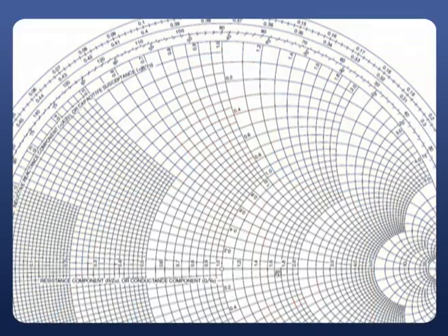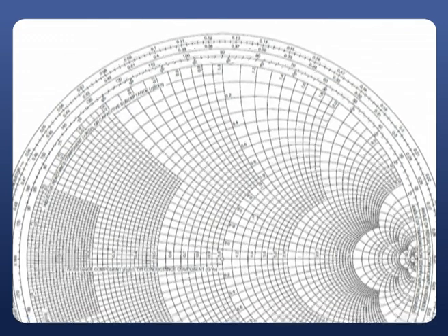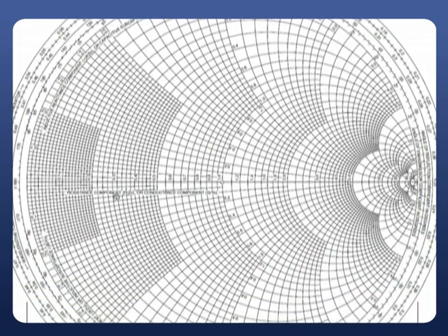Now, using that circle you can easily identify the standing wave ratio. How to identify the standing wave ratio using that circle? Just observe our Smith chart, and see where our circle meets the real axis. Whenever I draw a circle with this radius, the circle may lie like this. This is the imaginary circle that I am drawing, so actually it is not existing here. You can imagine a circle with OZL as radius and O as center.